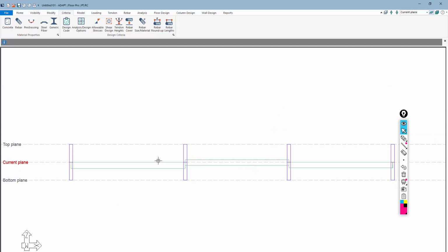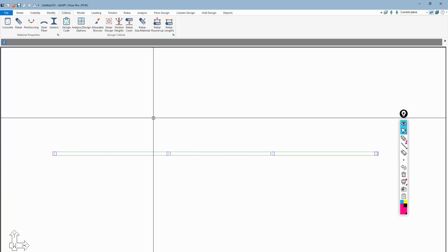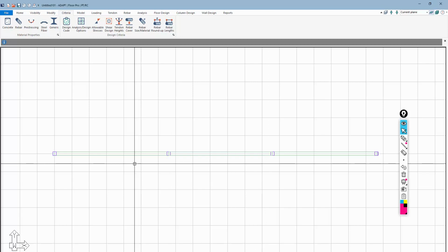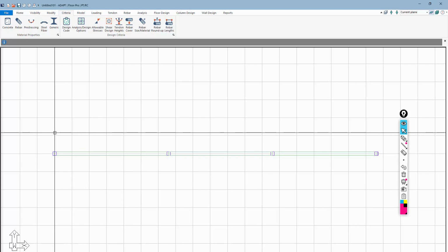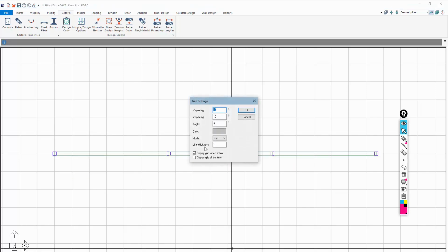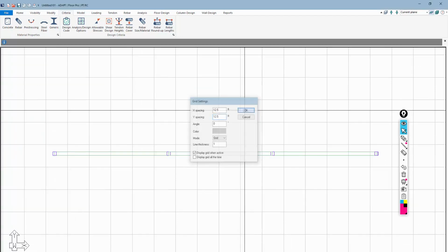The next thing, I want to add the slabs or the flange. So to model this, I want to be back not in the ZX plane, I want to be back in the XY plane. I'll just flip this back here to top view. I'm back in that top view. And if I turn on my grid again, we want to have, let's say, a 300 inch flange. And so we want the grid setting to be basically 300 over 2. So 150 inches, if we convert that to feet, we want the grid to be 12.5 feet. And we're going to just set this to 12.5 here.